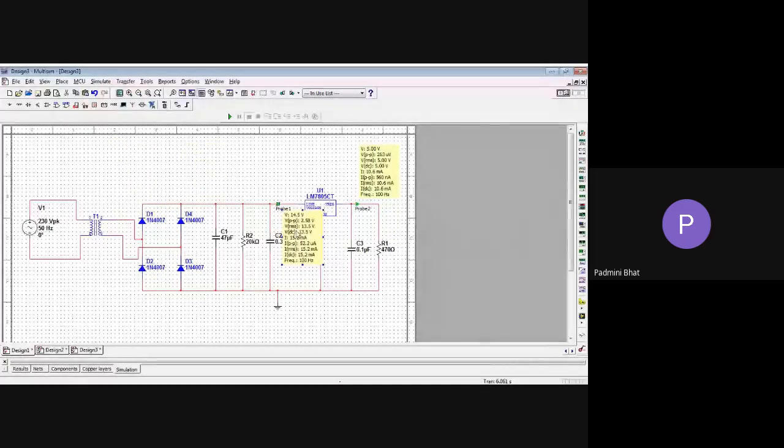See here, this is the circuit diagram for the plus 5. Check the diode connections and directions, then the values of the resistors, then the regulator specification.